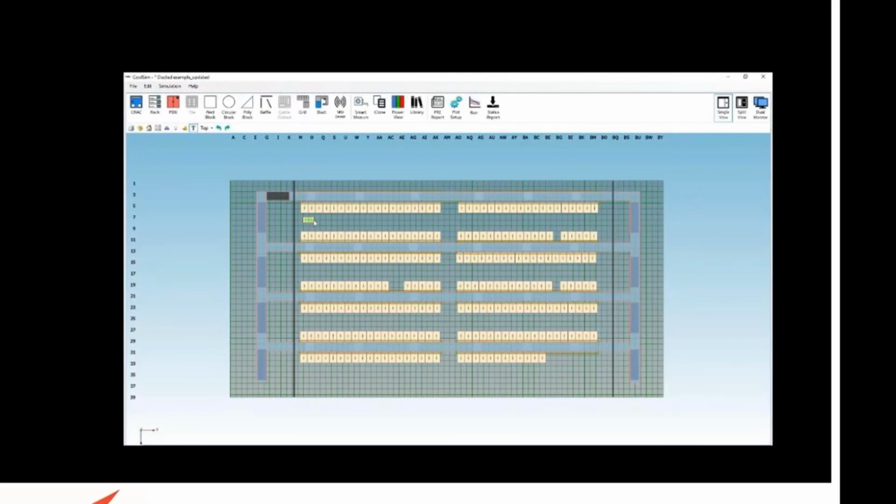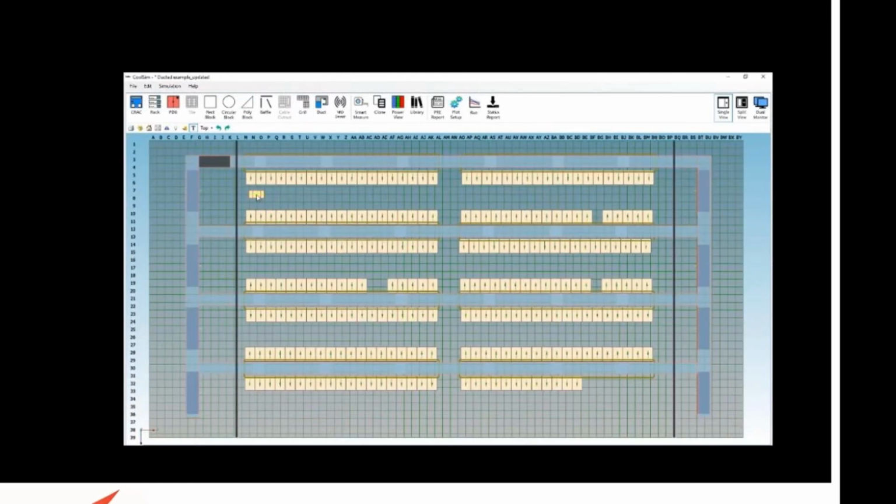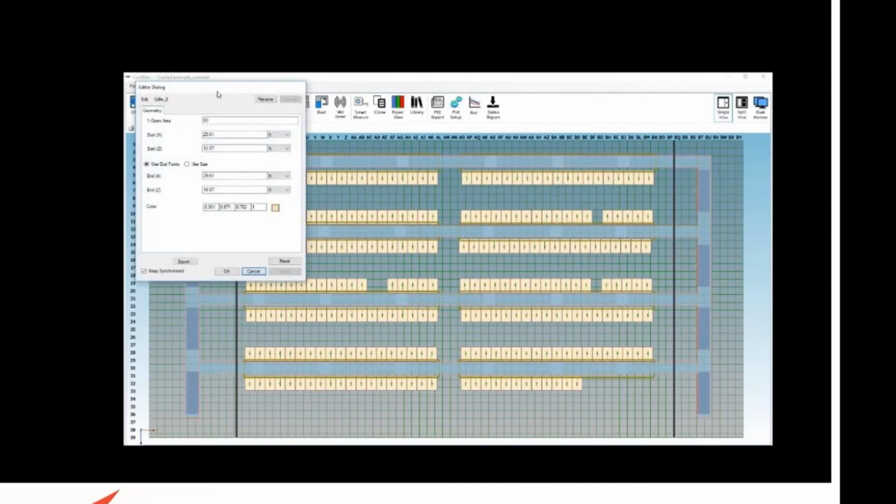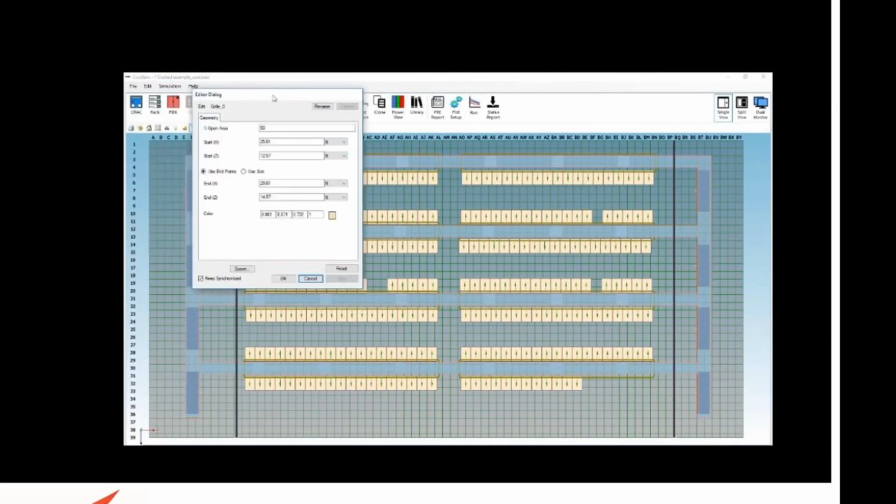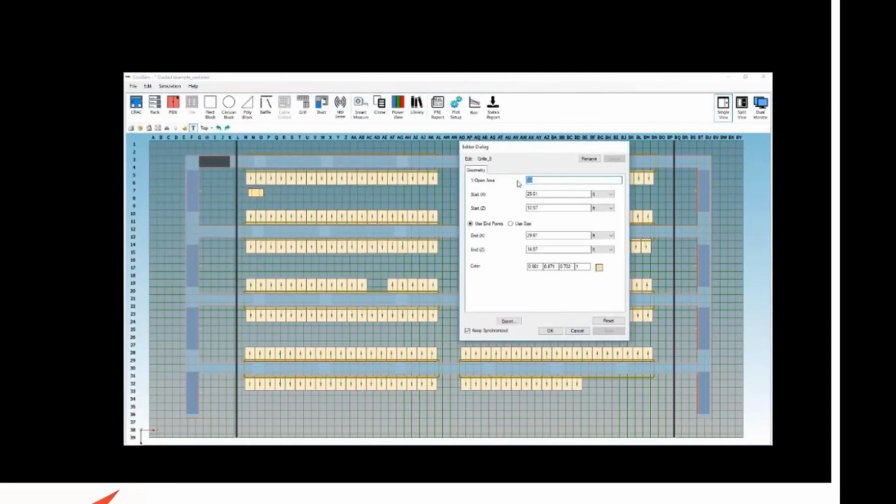Now I need to put some grills in. So I need to put some return grills. Got to let the hot air up into that ceiling plenum. So again, I get the first one set up and set the percent area open the way I want it, get the length in place. And once I've got one set up, I can use endpoints or size. I tend to use size unless I'm trying to match an end somewhere. I use size. You can guess at the size generally.